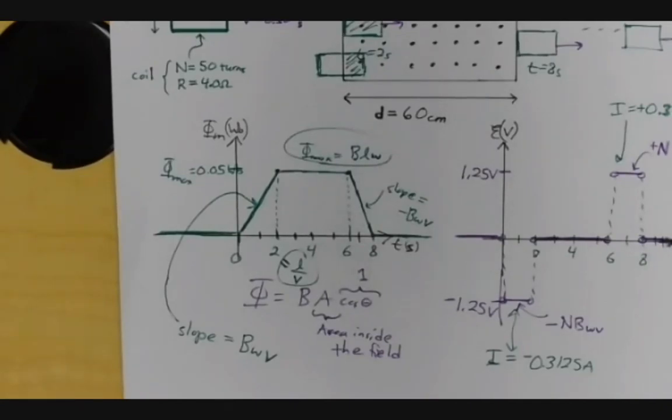But one nice thing about induction is if you want to get stronger effects, you can get more wire, at least from the point of view of voltage. Of course, if you make it a longer wire, its resistance probably increases along with its number of turns. So you'll get more voltage if you increase the number of wrappings. Anyways, that's it for this.